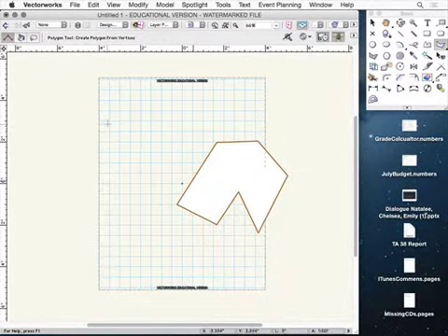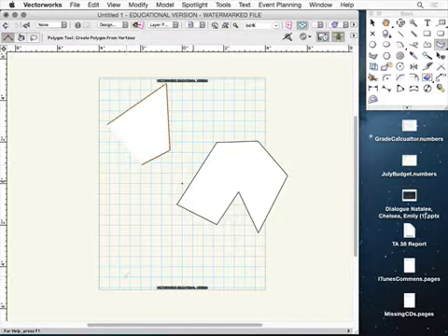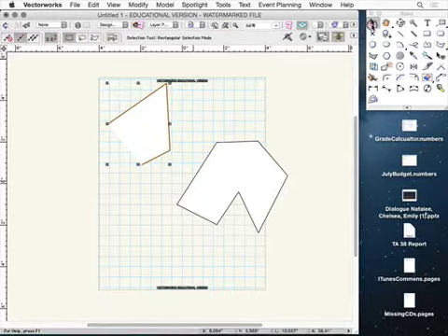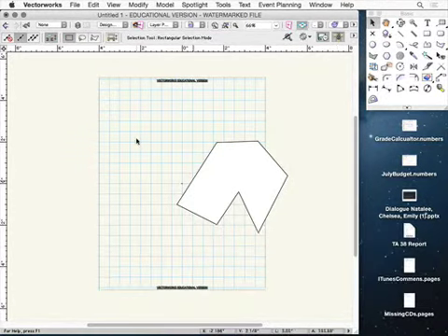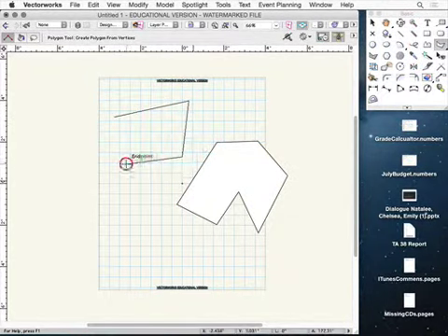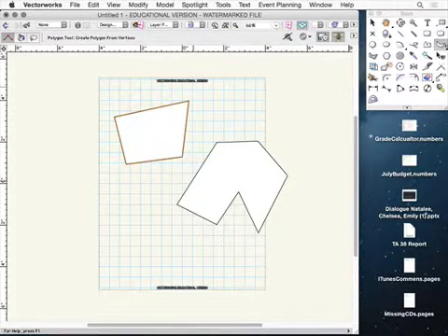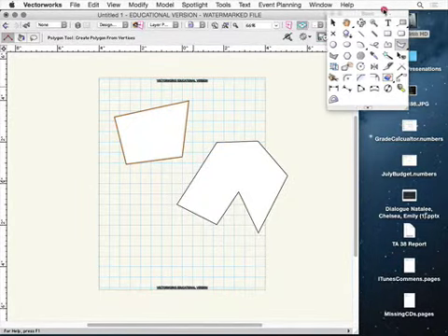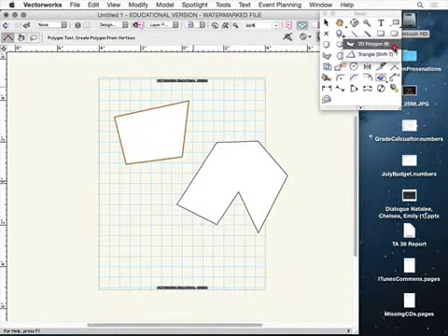Okay, you do want to make sure you close it though, because this does not have a line going across the end. It is not properly closed. This will go into 3 dimensions better than our polyline will, but not great. Okay, so make sure when you're using the polygon tool, you close it. Notice that the polygon tool has a little arrow next to it in the right-hand corner. That means there's a separate tool underneath.